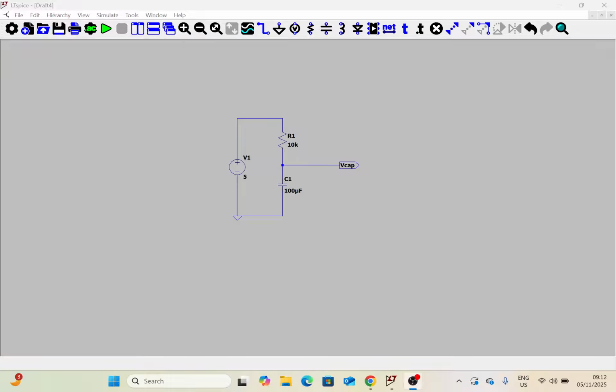In this video, I want to show you one directive called initial conditions, which you can use to affect how the simulation is supposed to happen. And what it does, just as the name suggests, is to allow you to set the initial conditions of some of the components so that you get to observe what you expect to observe.